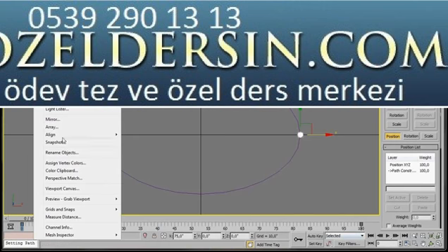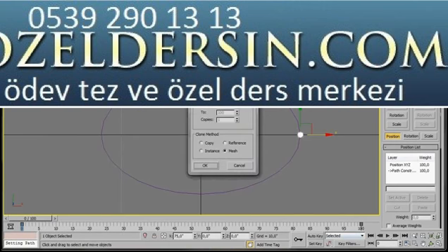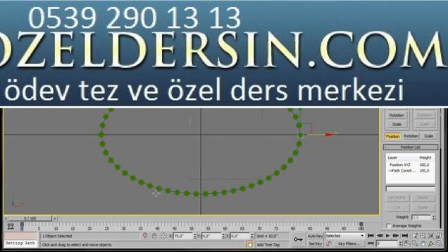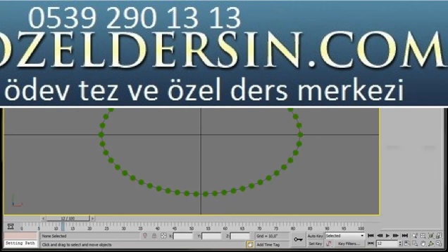Let's go up to Tools, or scroll down to Snapshot. Now here in the Snapshot panel, select Range, and we're going to type in 55 copies, and select Mesh as a clone method, then press OK. We're going to delete the sphere in the animation now, so just press the play button to find it, then you can delete it. Now we can select the ellipse.